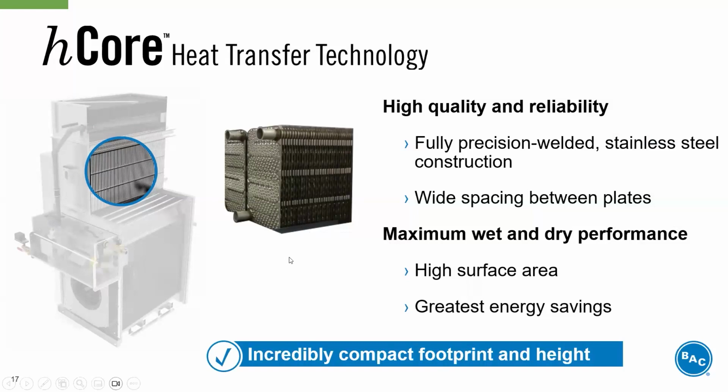So the plates are full stainless steel, and they are robotic welded at our factory in Milford, Delaware. The plates have wide spacing in between them. So this allows a significant amount of surface area inside the heat exchanger with a low air pressure drop across it. So that's what allows us to get excellent dry performance and also very efficient evaporative performance.